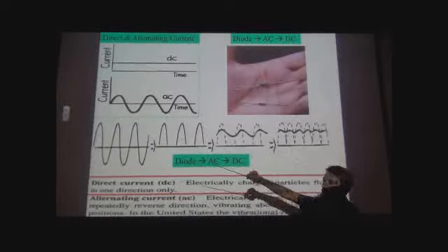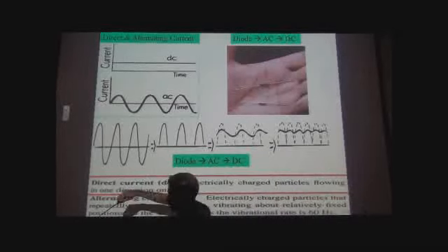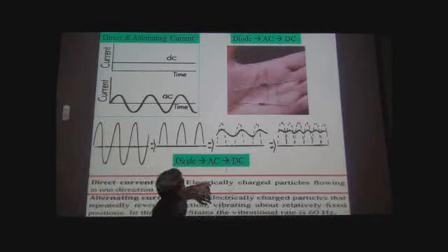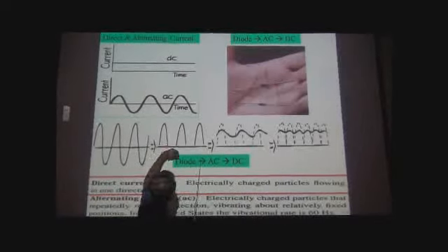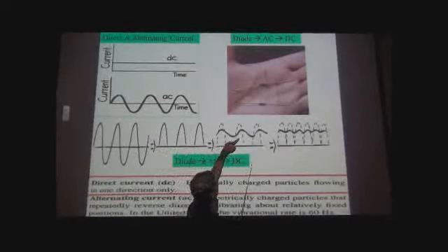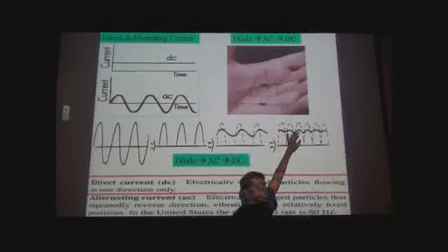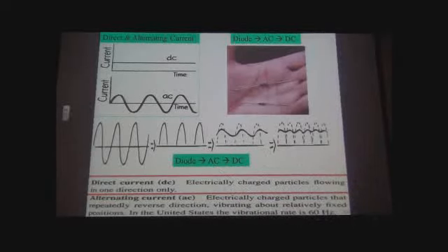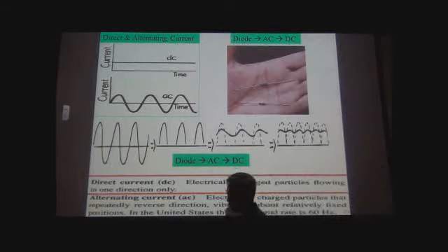And this is what happens when we get alternating current. The current that's coming out of the plug point is alternating. It oscillates back and forth. You put it into a battery eliminator or a direct current transformer, whatever you want to call it, for something like a computer. If you need it DC, there's electronics that takes this signal, cuts off the bottom or flips the bottom, and then you get a series of pulses, and then you can smooth this to give you close to direct current. So the diode converts alternating current into direct current. Direct current is charges that are traveling in one direction only. Alternating current is the charges keep changing direction, forward, backward, forward, backward.